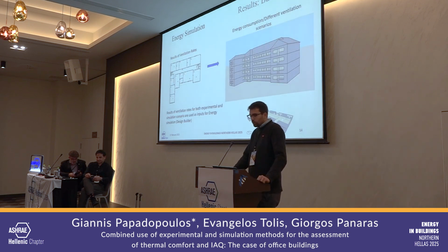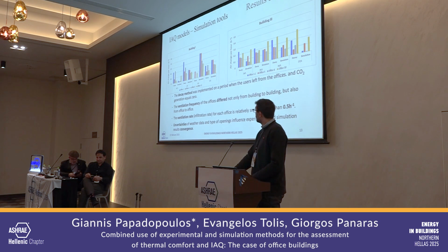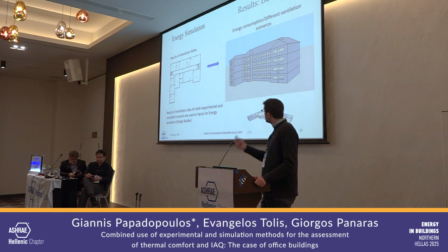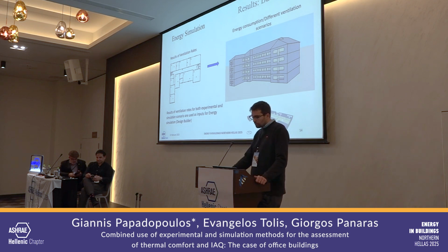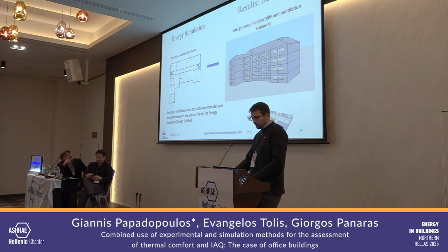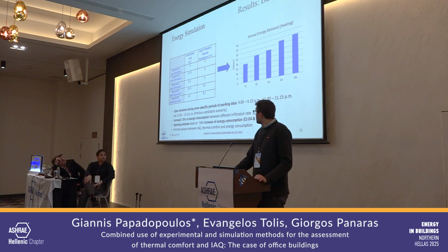So then we take this infiltration rate that we calculated from the measurements that we made using CO2 as a tracer gas and the CO2 decay exchange rates, and we put it in an energy simulation program, in our case DesignBuilder, to see the energy consumption that we will have according to different ventilation scenarios. Here we can see the 5 scenarios we simulated in DesignBuilder.